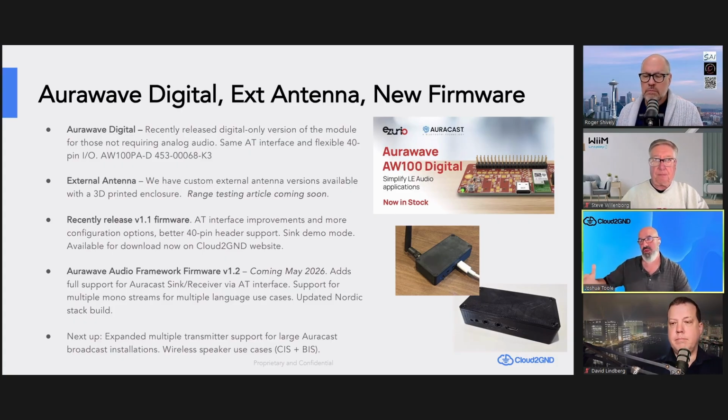As we see more things moving over to LE audio, I think we'll reach a critical mass point where it really won't make sense to continue to rely on Bluetooth Classic. Costs are reduced if we're able to drop the older technology. There's almost nothing done today with Bluetooth Classic except that final audio use case. So this is the last transition we need to make within the Bluetooth world to move everything over to the new radio architecture, which is greatly improved. It's a simplified architecture, it's more power efficient, and it's more cost efficient. I think this is the key driver for that.